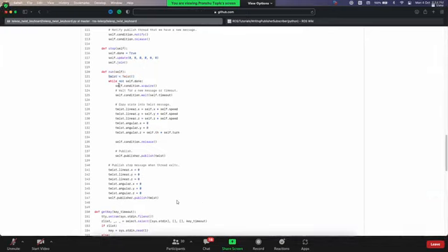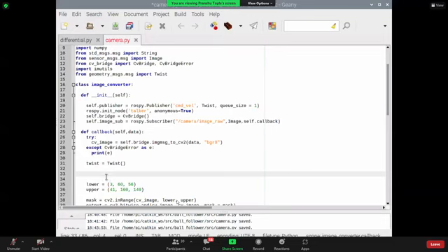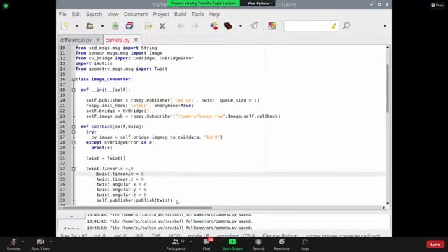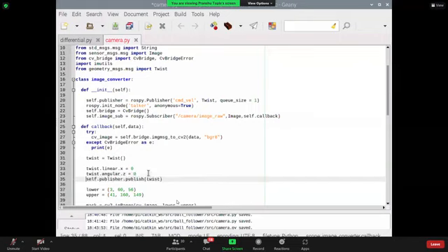Now what we have to do is twist.linear and theta. These are the important things that we want. So I will just copy them all first. So linear will be 0, and our angular Z is what we want. And then it is publishing the twist message.